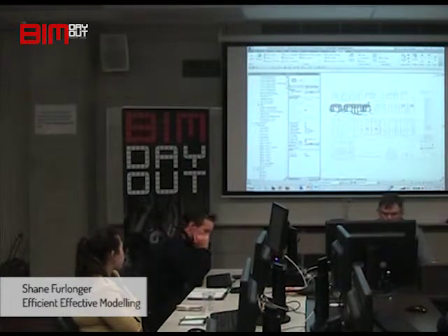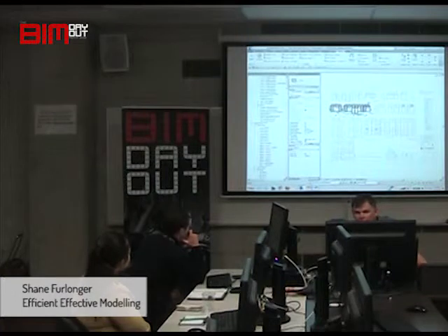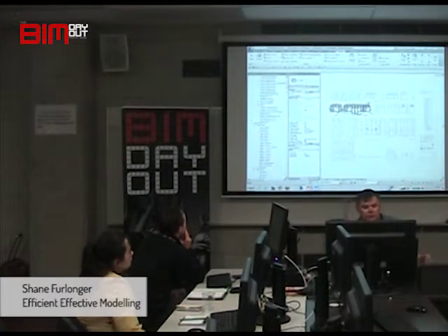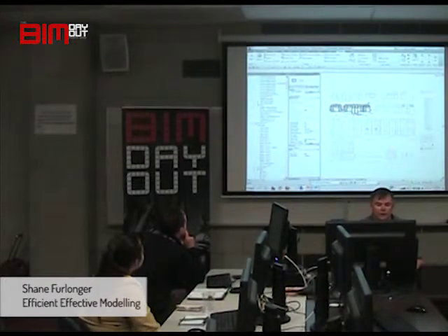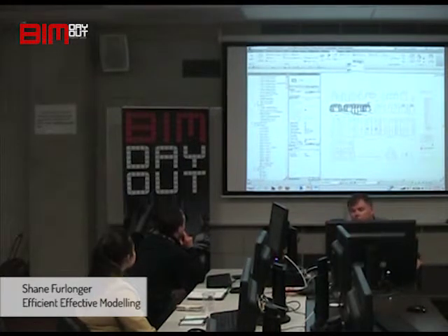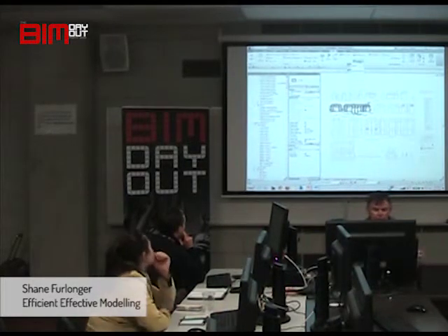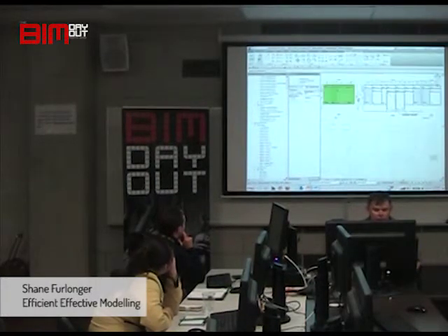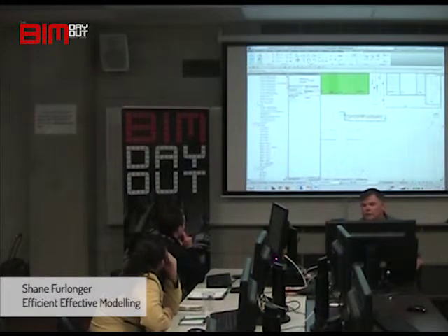Because if this was a legend created in a Revit legend, so I create a new view, I'm going to go to view and say create a legend. All I can put on there are 2D items, I can't tag them. And sometimes these get quite complicated, if I wanted to put on my tag, which I've got here, which is a real live tag, and tag that window frame or that window group.